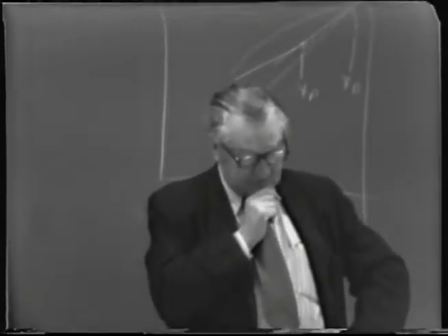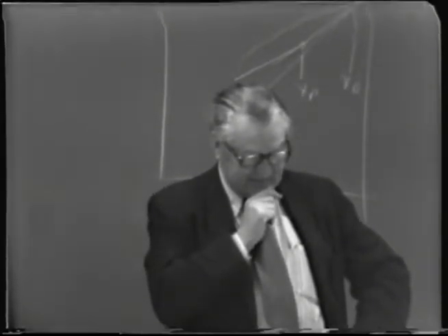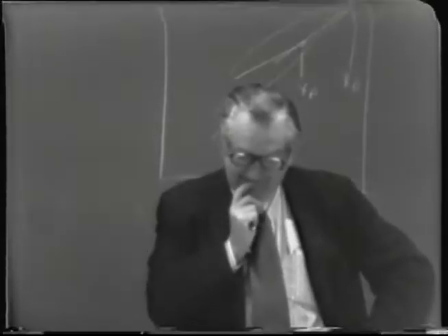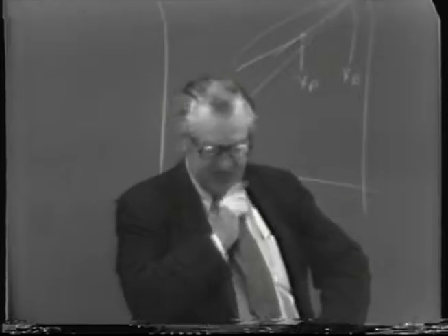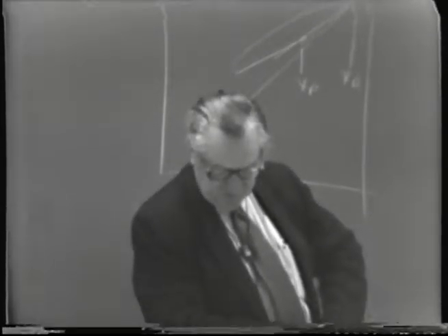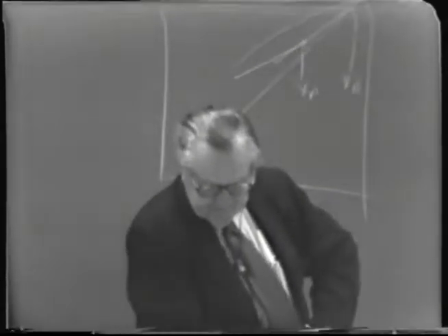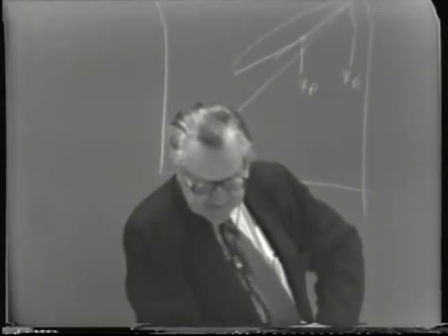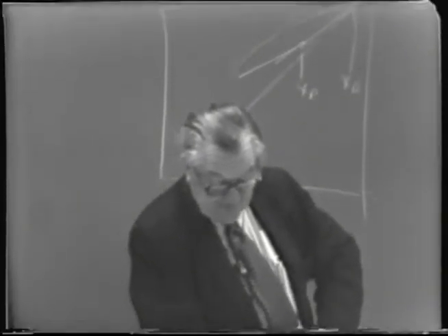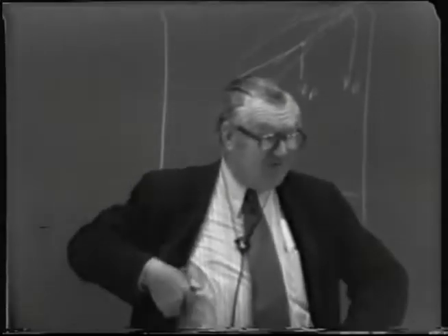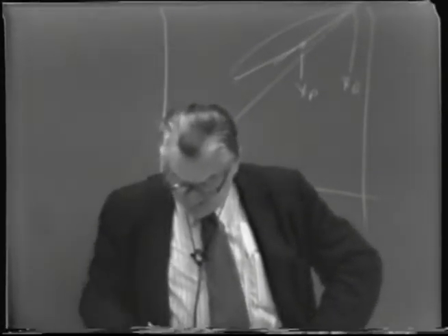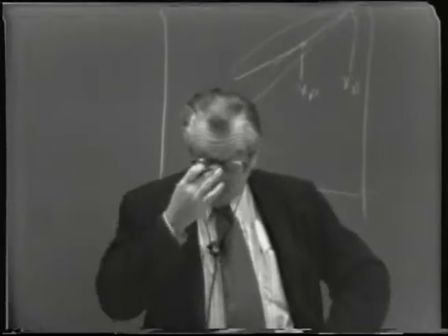Perhaps the butyl and the propyl alcohol would be one tray above it. But from a very practical sense, if you can find a tray that has an indicated proof of around 130 to 135, that'll be the plate where you'll have about the maximum concentration, and of course that's where you'd want to connect the draw-off point if you're trying to separate it.